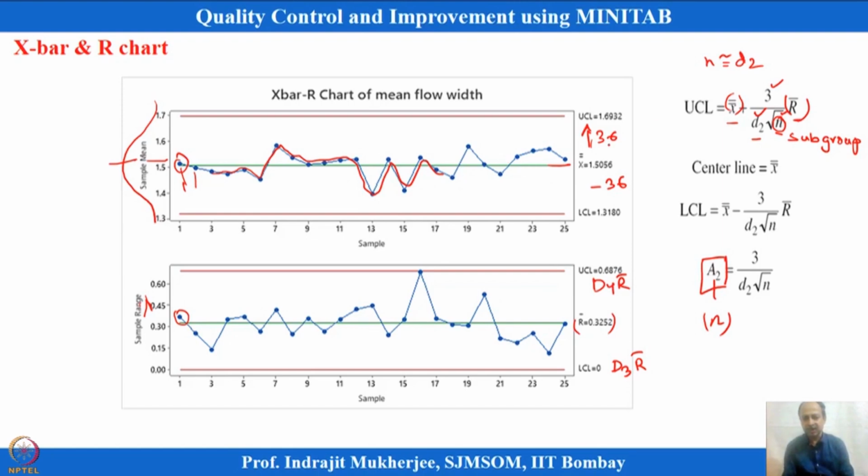In this case we can definitely say that this process is within control. In variability also we can see that the points are within the limits, and one point you see is on the line. We can consider a point on the line as a control point. If it is more than that, then only we will say that this is typically a signal, and then we have to take corrective action. If it goes outside the line, then we will take precautions.